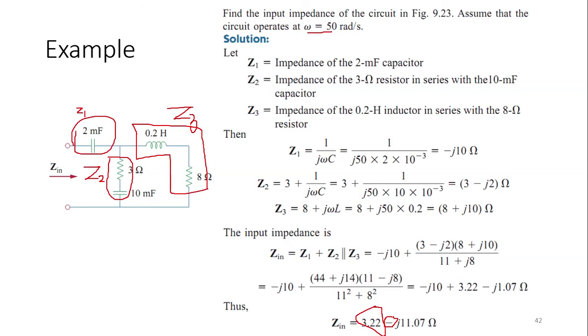A negative sign is used for capacitor impedance, as we have earlier seen. So the whole result is that Zin is a capacitive impedance. The power factor would be leading in this case.